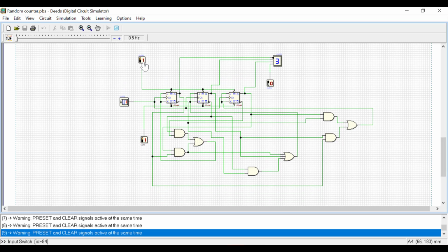Even if you take the flip-flops into an undesired state, still it is going to count back in the normal counting sequence we defined for the particular circuit. This is one way of avoiding the lockout problem. Now we'll see the second way of doing it in a moment.